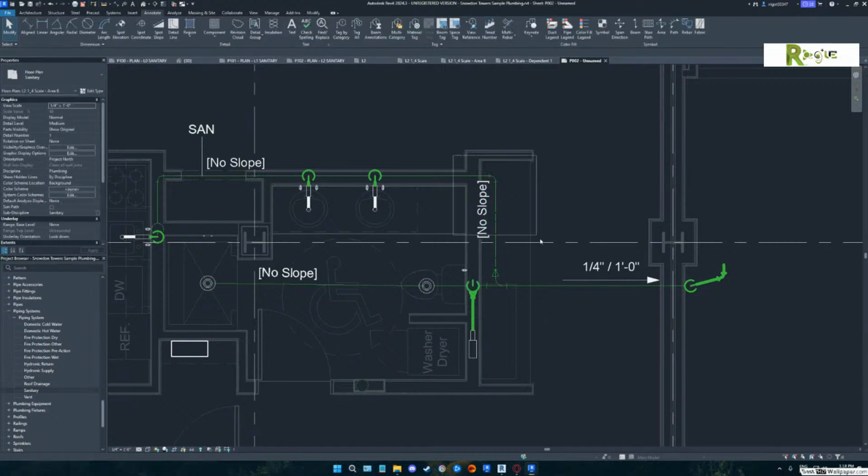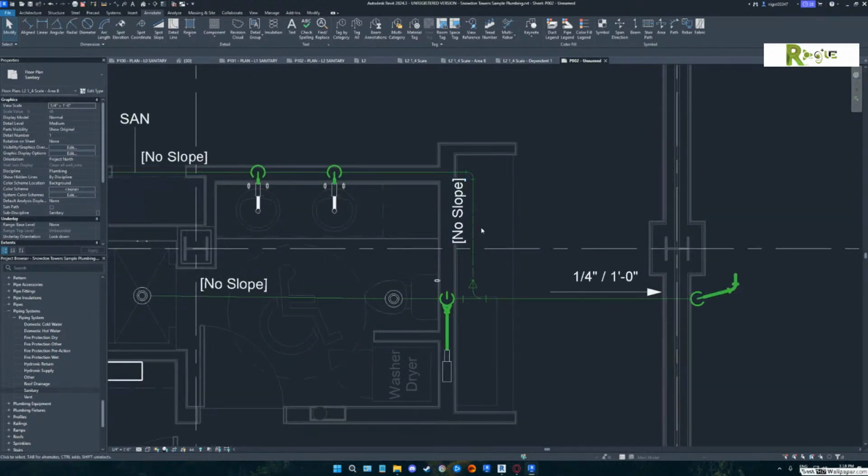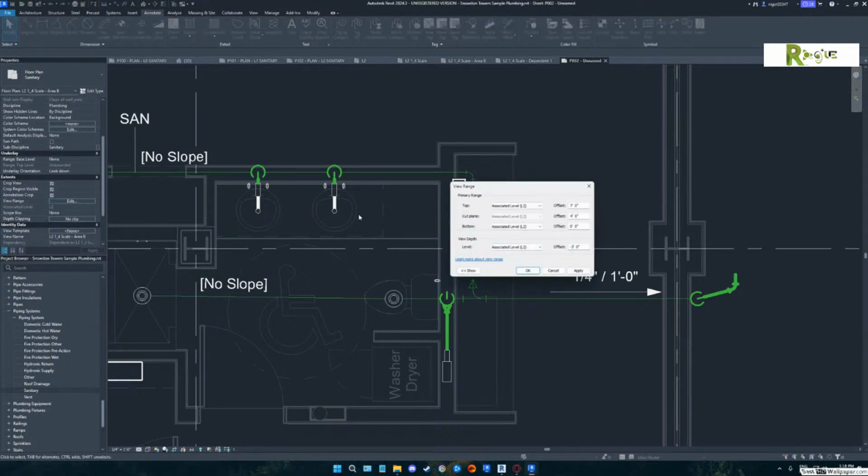All right. So notice how it's not selecting that stuff. That actually is odd. I think it has to do with where it sits in the cut plane. So if you go check your cut plane for this view, good answer, Eric. See where the view range is? You see where it says bottom and level? If the object is between the bottom and the level, you won't be able to window select it. So make your bottom say -3 feet.